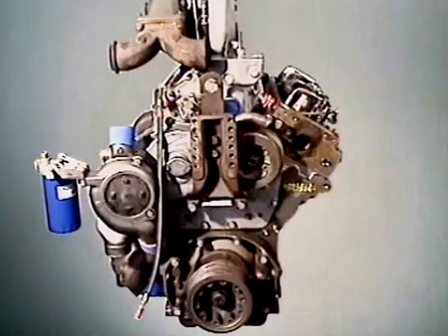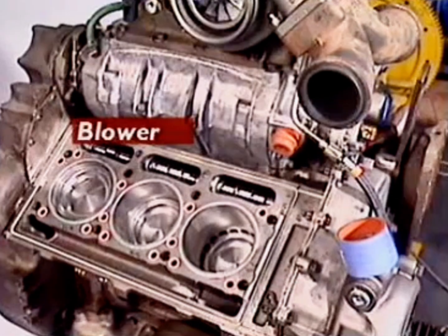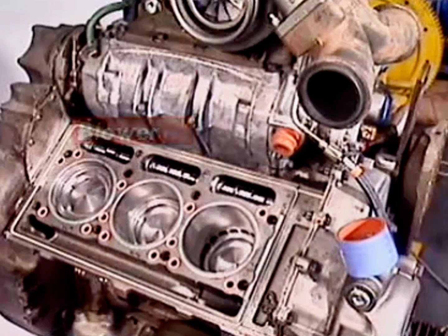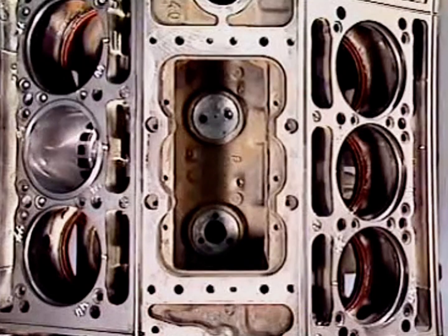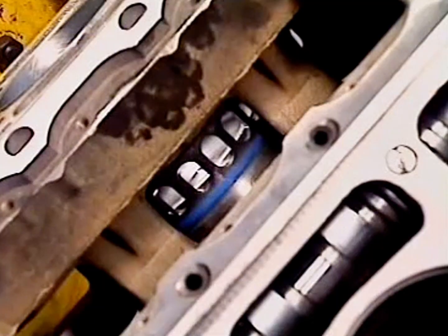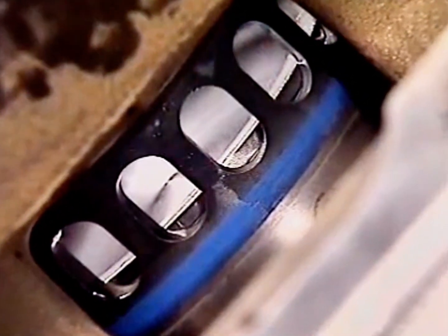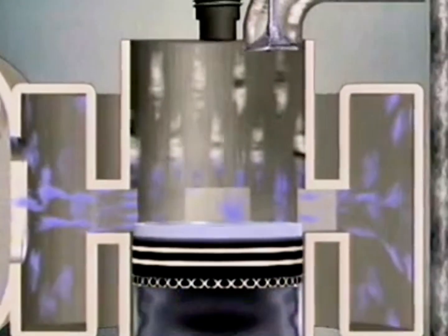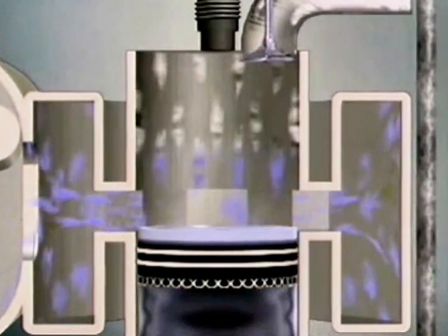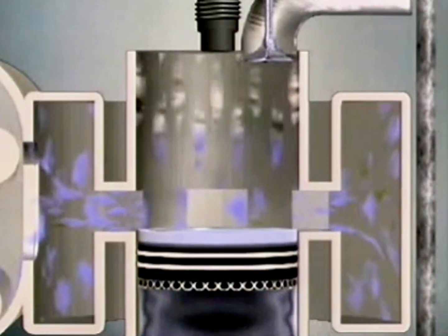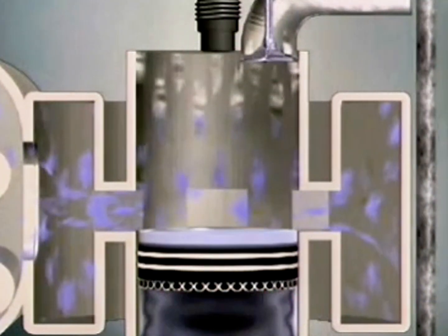In a 2-stroke diesel engine, an air pump or blower provides clean incoming air at pressure slightly above that of outgoing exhaust gases. The blower delivers air to an airbox surrounding the cylinder. When the piston uncovers the inlet ports, air enters the cylinder through a number of them around the cylinder walls. This fills the cylinder with fresh air and helps blow out exhaust gases. Removing exhaust gases is called scavenging. Without effective scavenging, diesel engines lose efficiency.